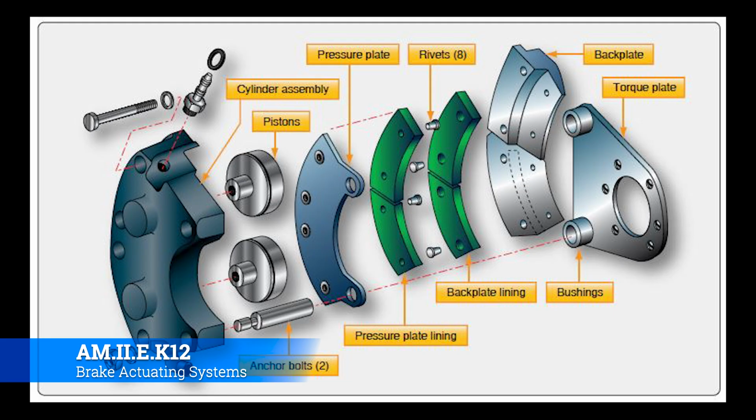Now, there are special brake pad rivet squeezers that you can get, but you can also just use a regular rivet squeezer if you have the right dies for it. Anyways, they squeeze on and onto the pressure plate. Then those linings push up against the brake plate and cause the aircraft to stop.